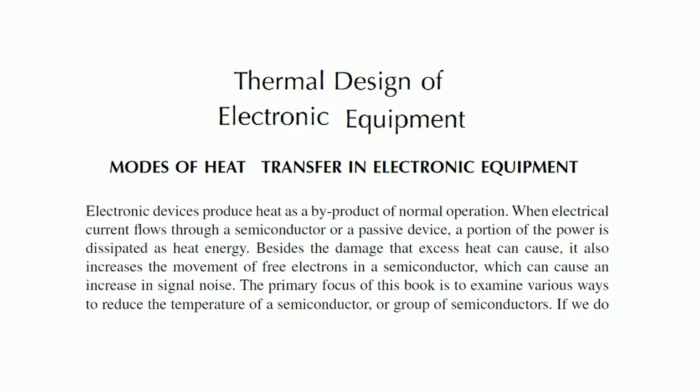It has in the on condition a small voltage and a large current, and in the off condition a large voltage and a small leakage current. In spite of the best switching transistors, the best switching semiconductor devices, there is a rate of switching, how quickly it turns off and on. That little period required for it leads to heating.